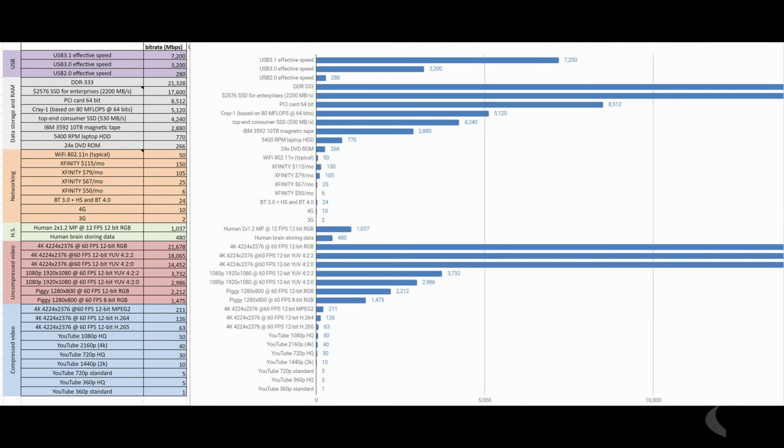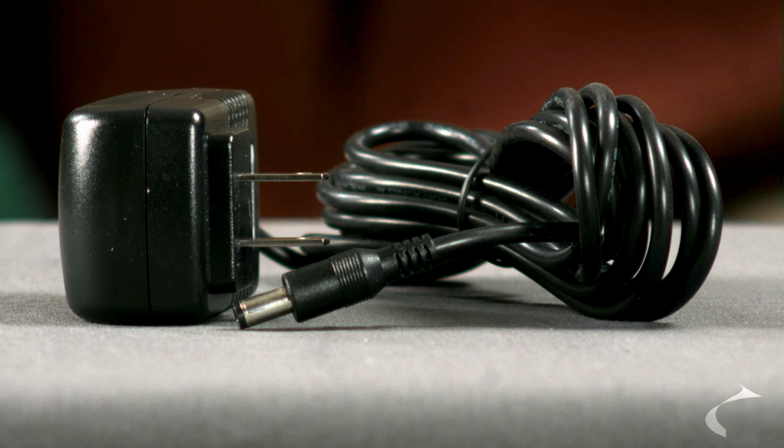SUB2r camera needs 3.7 gigabit per second for video transfer for 4K at 30 fps, 1.85 gigabit per second for 1080p at 60 fps, and the host should be able to provide 5 volts up to 3 amps to adequately feed the camera's onboard processor. Not all computer manufacturers adhere to the USB specifications when it comes to power supply. For those scenarios, use auxiliary power. Use SUB2r certified power supply which provides 5 volts and 3 amps of current, included with the camera.